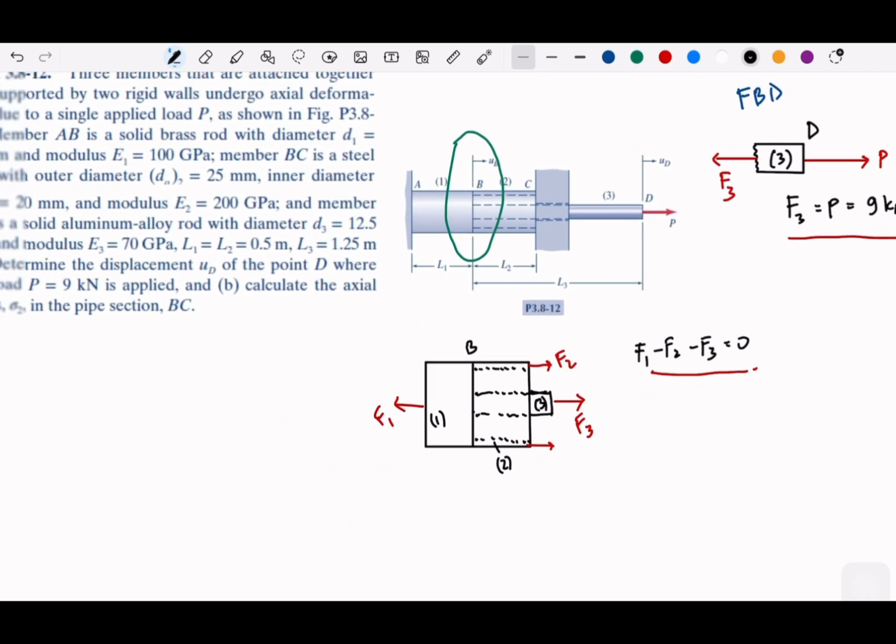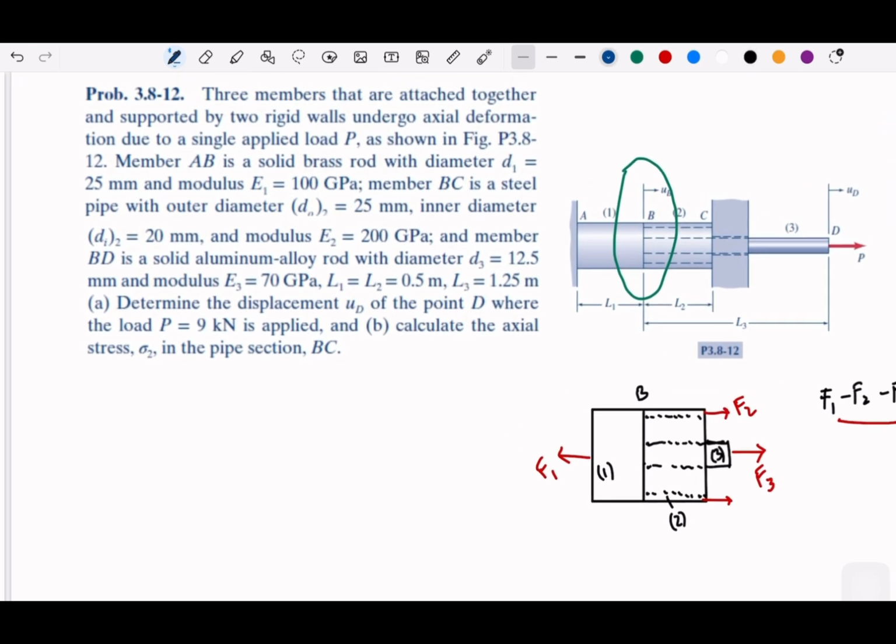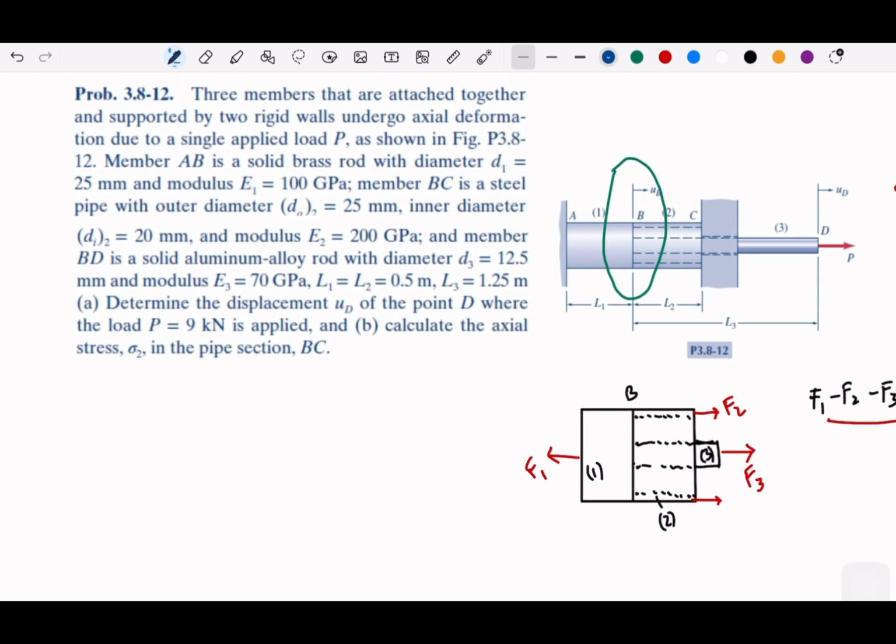and I believe that is the first starter. Okay. The second part is it will be having some displacement, right? It has some displacement, so we can write down, so every time you are dealing with problem in axial deformation, we can start by just writing the formula FL over AE. Okay, we can simplify.